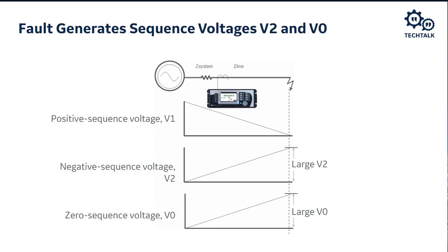So what that means to us is that we might have a problem if our impedance in front of the relaying location is very large compared to the impedance behind the relay location, because we need to use a polarizing quantity to determine the direction of the fault.